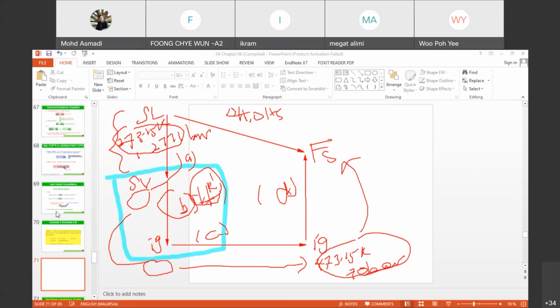But if you deal with this one, because the pressure is 70 bar, so which equation for you, Ikram? You can use Lee-Kesler correlation. Okay, you can use Lee-Kesler or Peng-Robinson. So I think you can understand. And then I think for the ideal gas condition is easy, right?